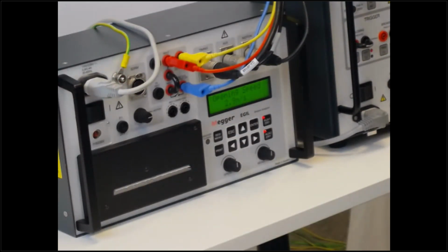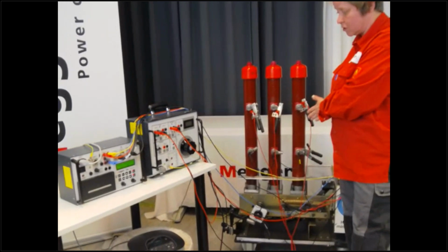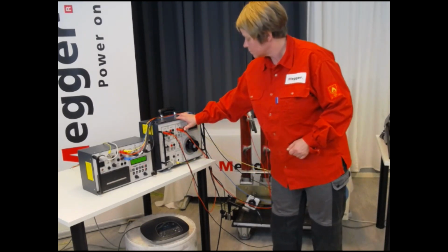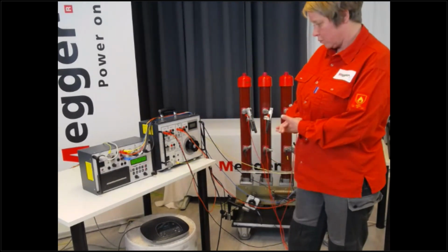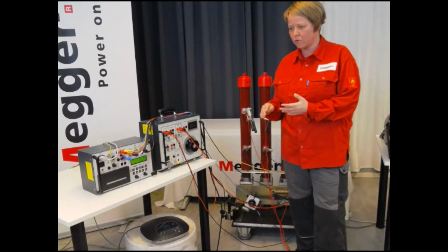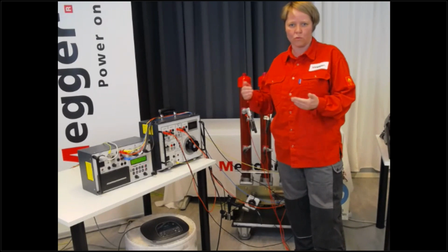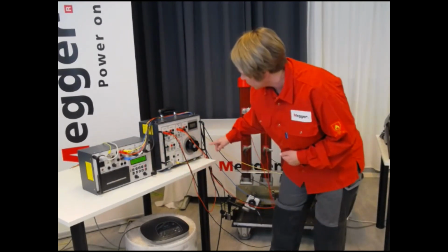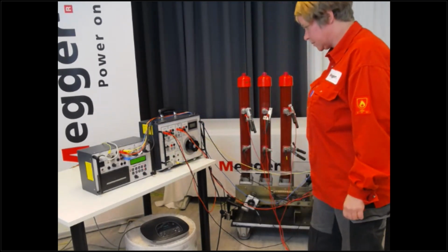What you can do is also, of course, measure multiple operations. But since this one is not connected the whole time to the supply, I need to charge the motor again. And what are those multiple operations? Marius mentioned them before: you want to simulate different things, like you connect the circuit breaker to a fault, and how quickly does it open again. So you can do an operation like a close-open. Again, I have to check my supply, and it's going to be a multiple operation now. A little bit noisier, but.